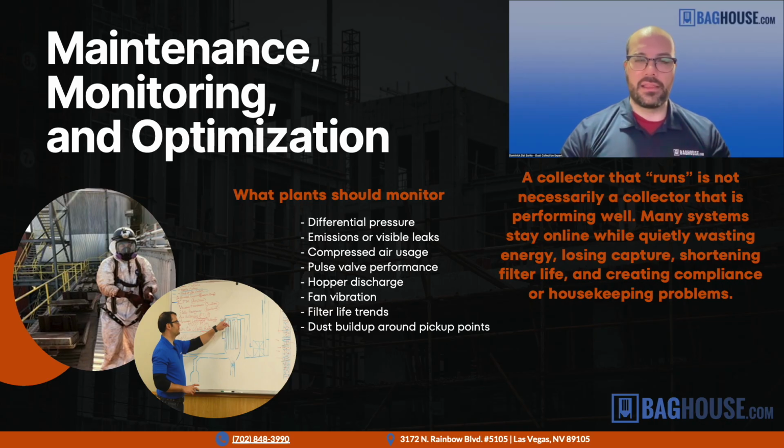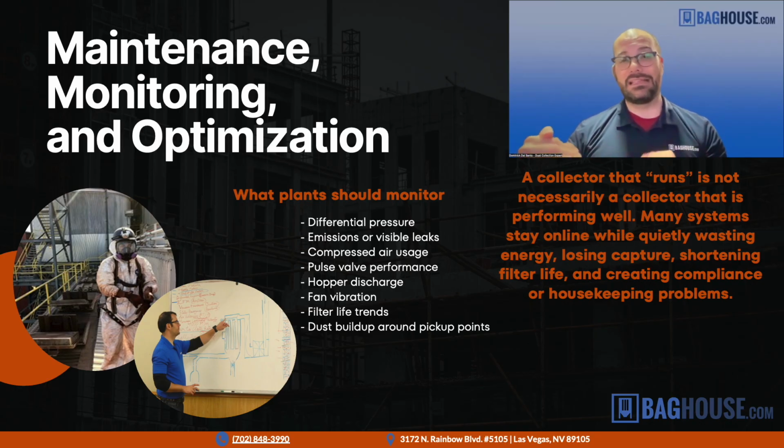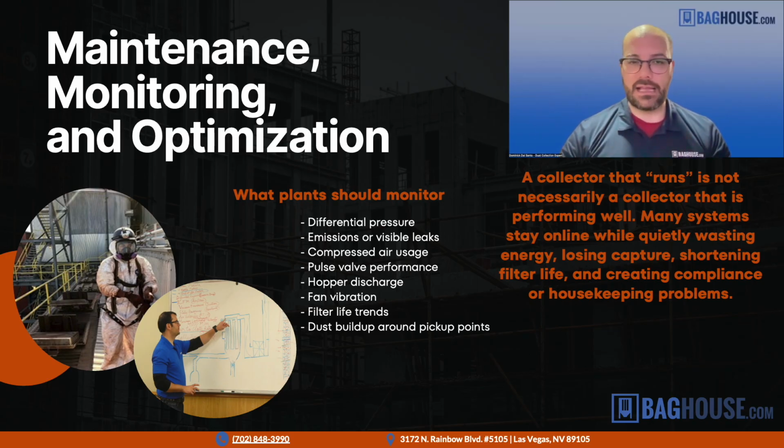And then finally, a lot of things that cause poor performance in the dust collectors can be traced back to shortcomings in the maintenance plan. So using the wrong kind of filters, letting them run too long, not taking care of these basic regular maintenance tasks. But some of it comes back to design flaws. So things like using the wrong filter media, undersizing the dust collection system, not designing the hoods or the source capture very well, or as we said, modifying it over time, adding more pickups, diverting things around, butchering and chopping up and pasting back together the ductwork.